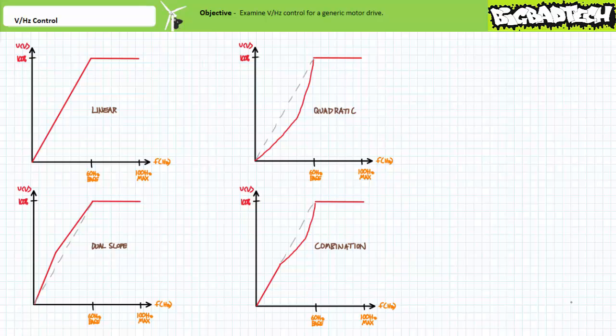Again, the complexity of volts per hertz profiles can range from the simplest fixed linear profiles defined by a base frequency only, to an extremely application-specific curve depending upon the functionality offered by a specific motor drive. Alright, that's really about it for volts per hertz control. However, before we bring this lecture to a close, let me make a brief comment about units directly related to an upcoming lecture on acceleration and deceleration profiles and ramp times.